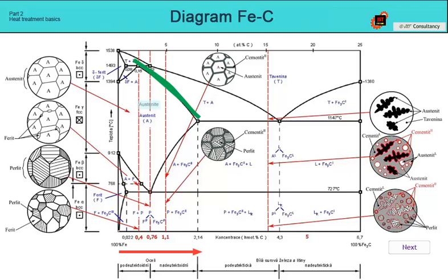At the lowest point of the austenite area lies the so-called eutectoid point, which divides the steel region roughly into two halves. The eutectoid point corresponds to a carbon concentration of 0.8% at a temperature of 727 C. In the range of carbon from 0.022% to 0.8%, there are so-called hypoeutectoid steels, in the range above 0.8% to 2.1%.